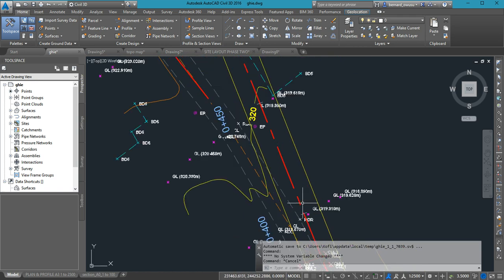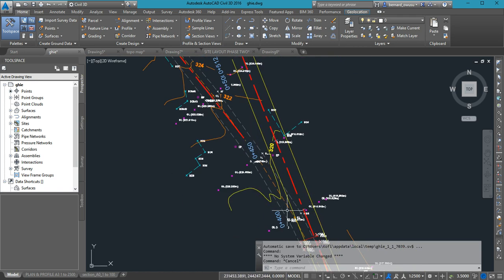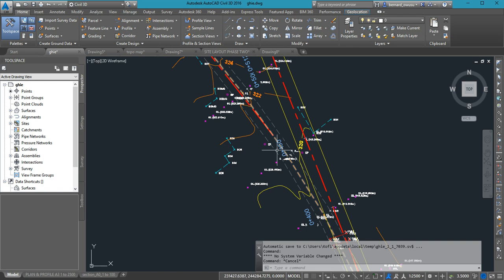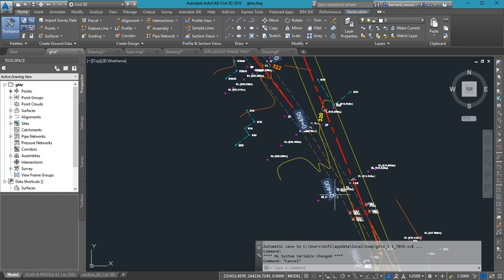Now I'm going to put in a curve. If you look at it, you can see that the deflection is very small. So it means that obviously the radius here will be very large. You don't have to worry yourself with any mathematics or verification. You will see that here you need a simple curve. It's where you are in doubt that you may want to first put in a simple curve, then check. If the radius is below 330, then you change and rather put in one with spirals.